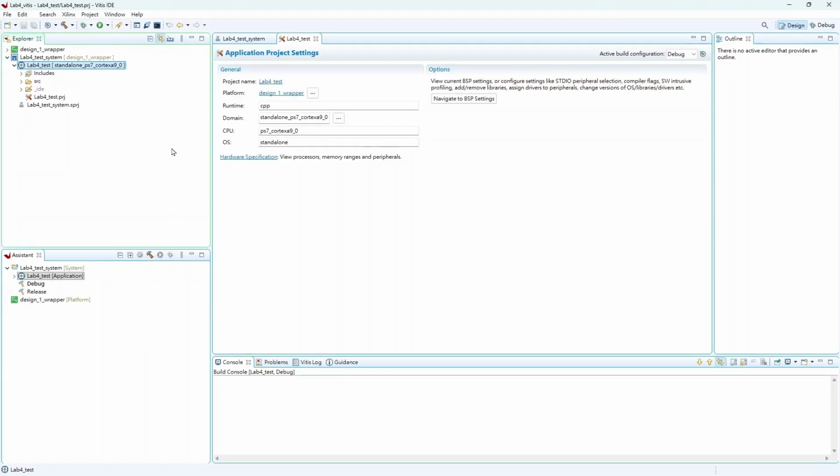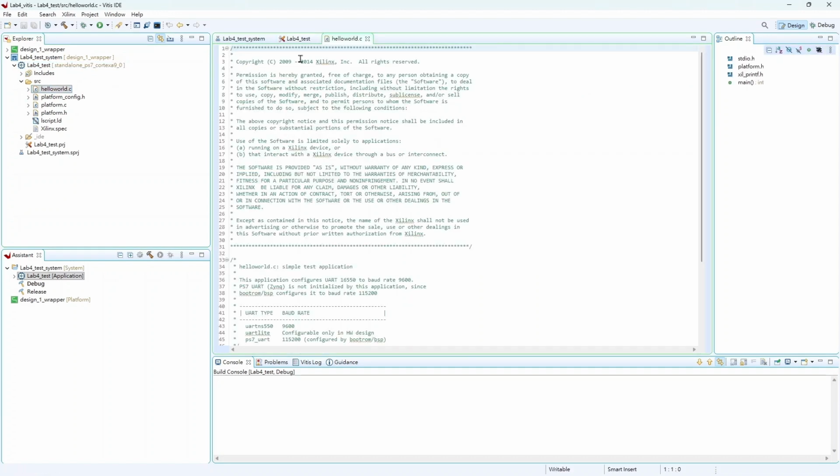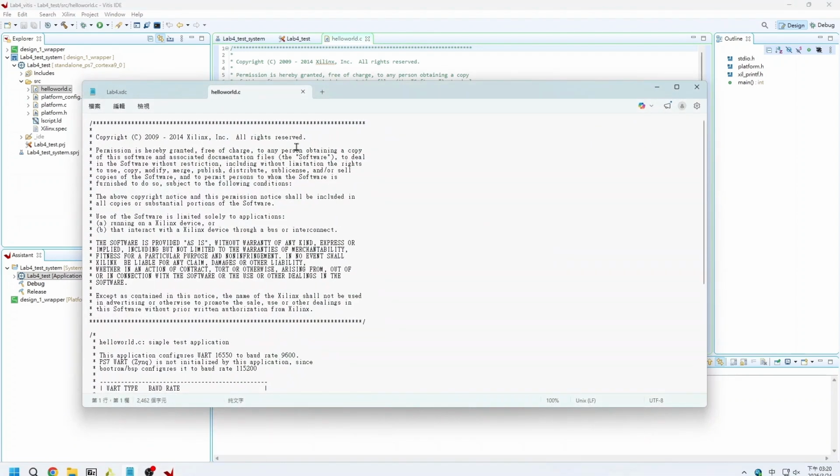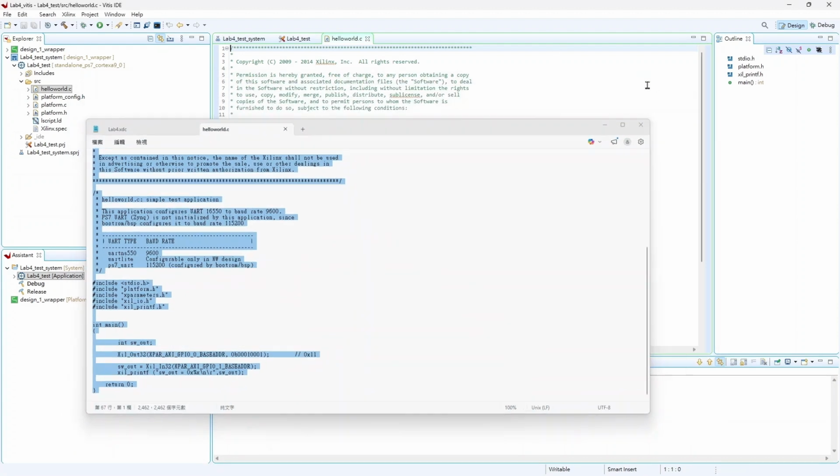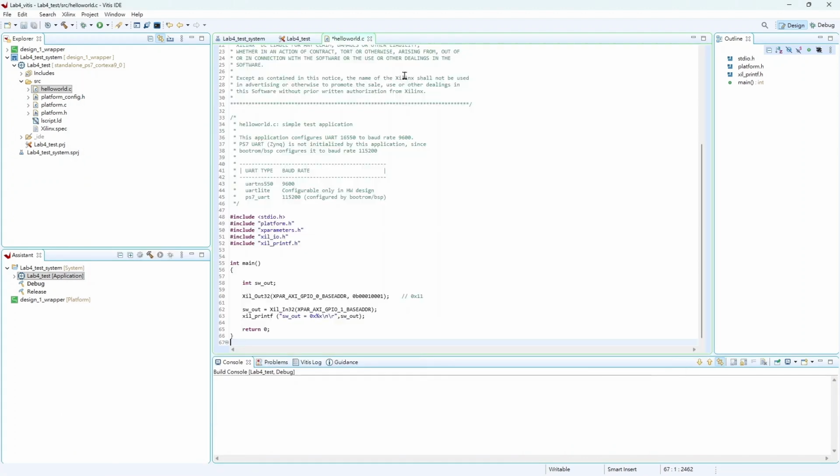After the workspace finishes initializing, you will notice your newly created application project along with the hardware platform XSA structure listed on the left Explorer pane. Expand the SRC folder, open up helloworld.c, and we will rewrite it to implement our required functions. Simply copy and paste our sample C code template right here. This code contains the foundational memory mapped read and write instructions for our experiment.